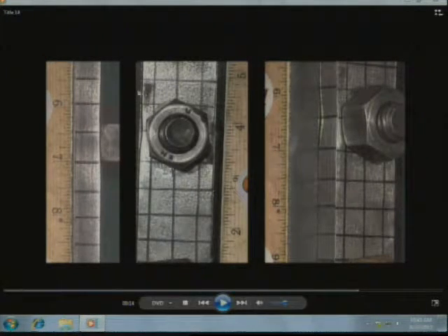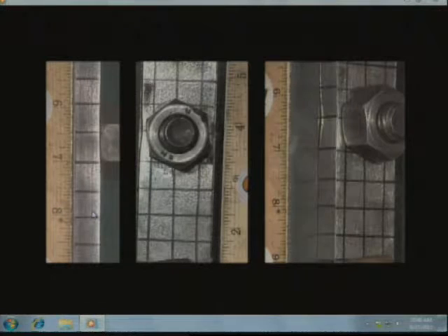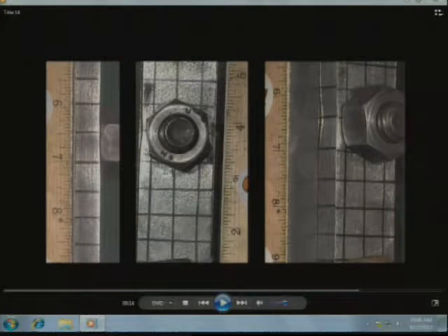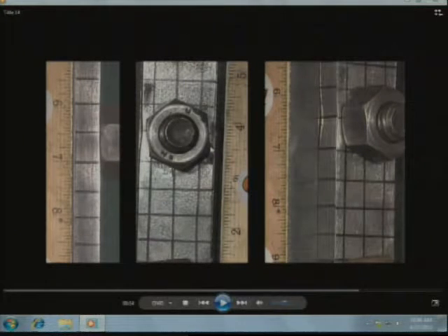Okay? And actually, if you compare the elongation, it's not even very much. Look, these tick marks are about the same size all along the length. It's yielded locally, and who cares? You with me? Okay, we can keep going. Now that's a little troubling, right? That's a little troubling when you start to see it neck in. That's when you probably want to run, if you see that in a real structure. Depends what the loading is like.